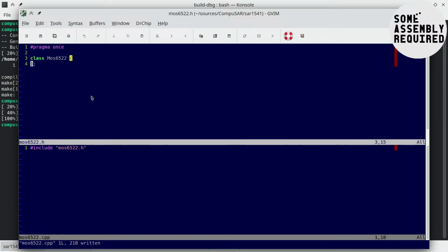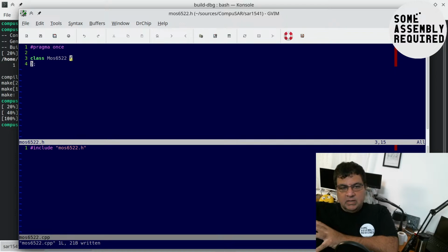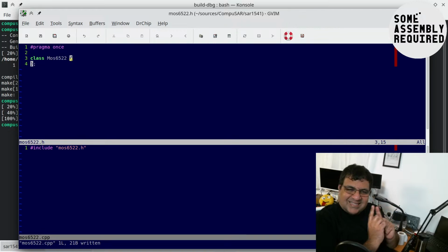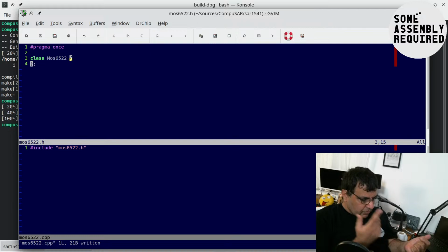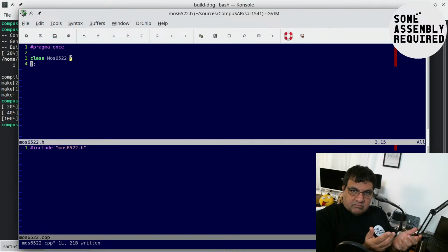But sorry, before that, we need to decide how we implement the CPU facing side and how we implement the outside, the interface facing side. So the CPU facing side will implement pretty much the same way we implemented the CPU. The CPU facing side are requests, right? They do read this register or write this register, basically. So we'll implement those directly.